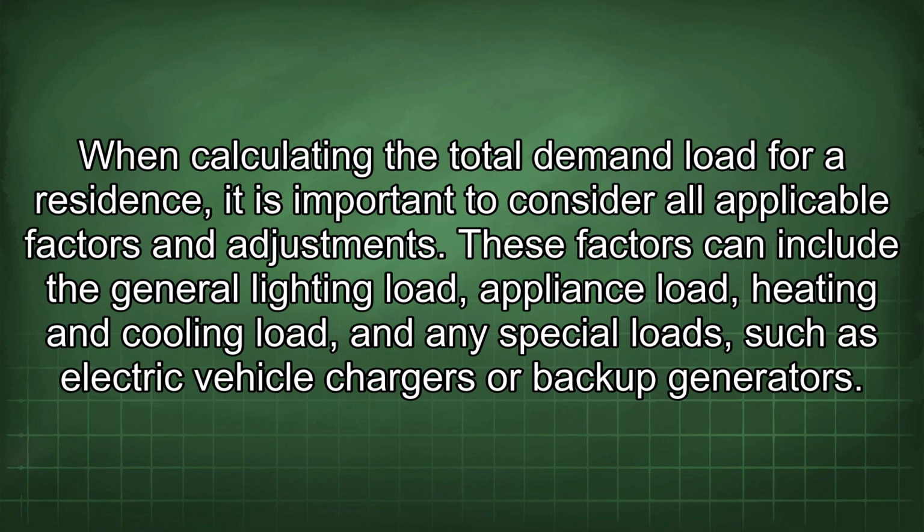When calculating the total demand load for a residence, it is important to consider all applicable factors and adjustments. These factors can include the general lighting load, appliance load, heating and cooling load, and any special loads, such as electric vehicle chargers or backup generators.